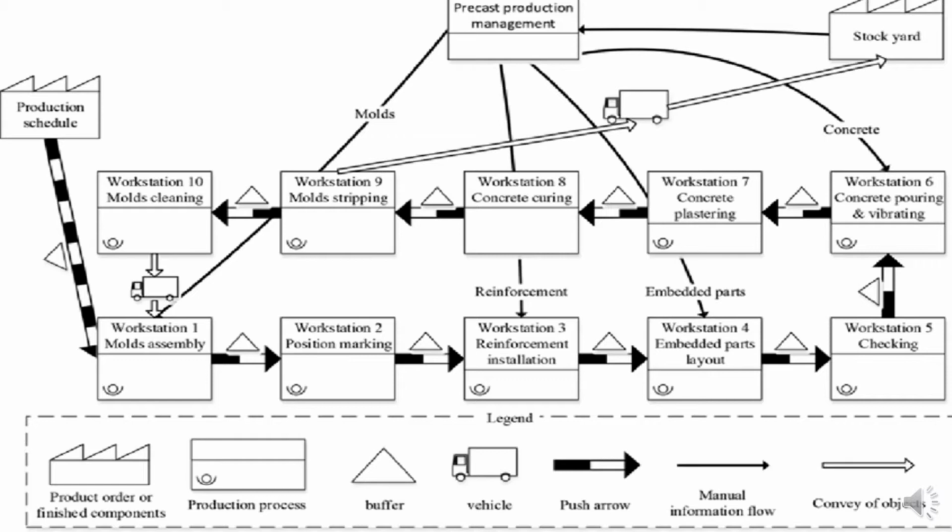Many precast works now employ computer-controlled batching plants. Compaction of concrete using a poker vibrator. Compaction of concrete to ensure that optimum density is obtained and that specified strengths are achieved. Concrete is placed and compacted using high-frequency external vibrators or pokers.